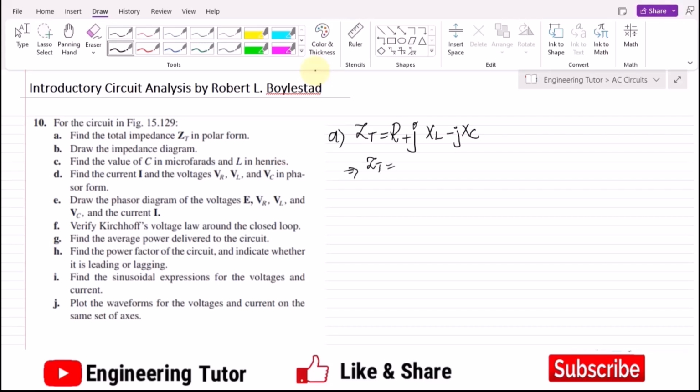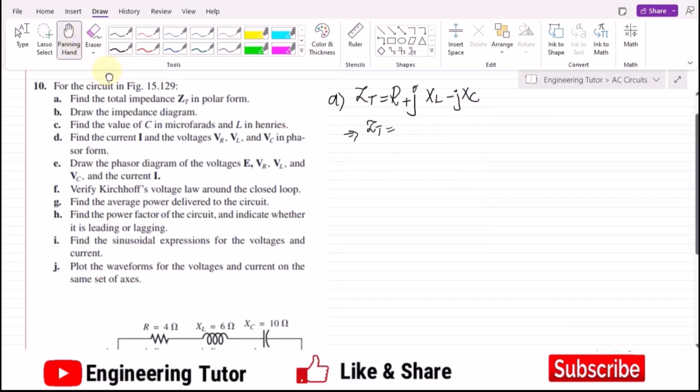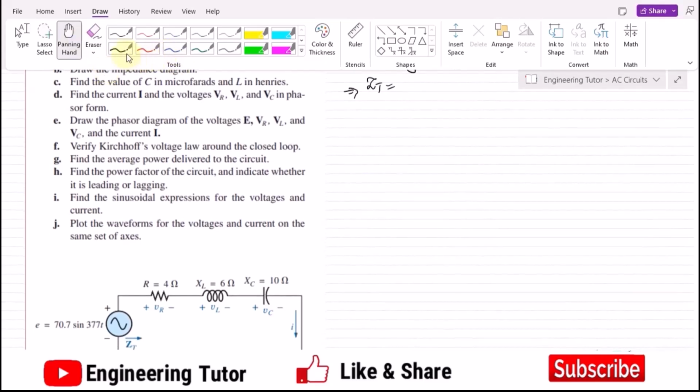Z total is equal to the value of R, which is 4, the value of XL is 6, so this is j6, while the value of XC is 10, so that would be minus 10. Now calculating them, what will I get?